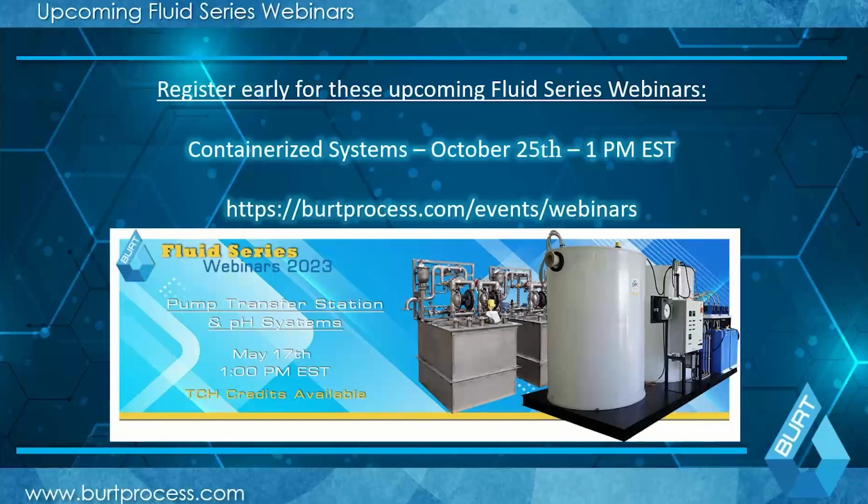There are different designs. A lot of standard lift stations utilize a top vertical mounted pump, and when you do that, you only have a certain impeller depth, which can be about 11 inches for a non-bearing style pump. If it's a bearing style pump, it could be considerably lower, but for a lot of smaller designs, a bearing pump just isn't practical. So most people will say if you're using a standard vertical pump, you need to be about 10 inches from the rim.